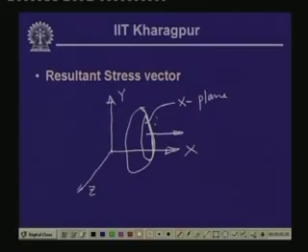Now, on this x plane we have, at a particular point, a resulting stress which we call R. If we take the components of this stress R in 3 perpendicular axis directions, then we have a stress acting in the direction of x, which is normal to this section, and as per the definition of normal stress, this is the normal stress acting in the direction x.